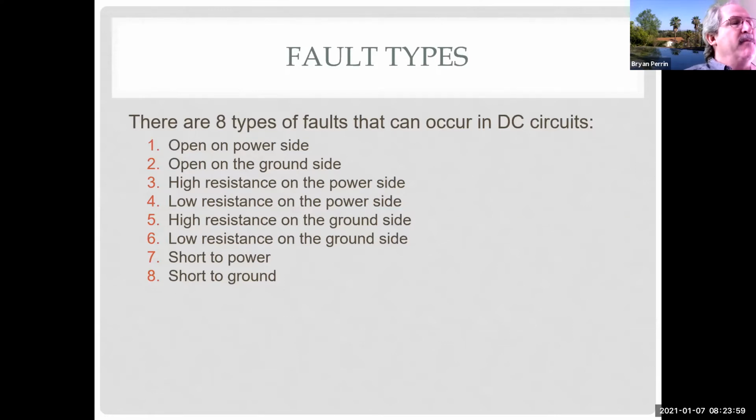I can get high resistance on the power side or low resistance on the power side, high resistance on the ground side or low resistance on the ground side, a short to power or short to ground. So electrically, those are the faults we can get. Now, of these 8 faults, there's only 4 faults we're going to diagnose.